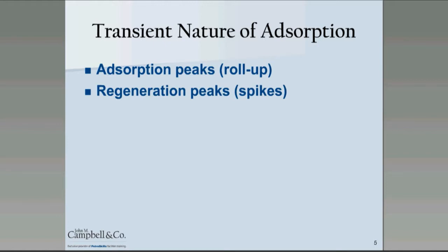This occurs because there is always some amount of active molecular sieve in the bed. Let's first talk about the adsorption peaks. From the previous table, we can see that hydrogen sulfide and ethane will be admitted into a type 4A molecular sieve. Now, water is much more strongly held than H2S or ethane in the pores. So water is going to displace any H2S or ethane that may have gotten to the pores before the water.